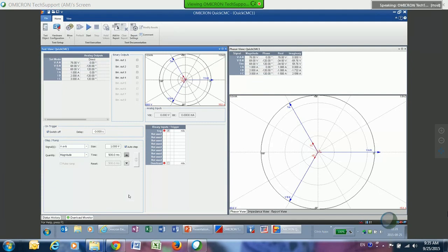And so now if I click on the up or the down arrow, every half second it is going to ramp it up or down 1 volt. This may be difficult to see on your screen as far as timing, but it's just automatically ramping for me. Or I can ramp down if I want. And if I just uncheck it, then it'll stop.